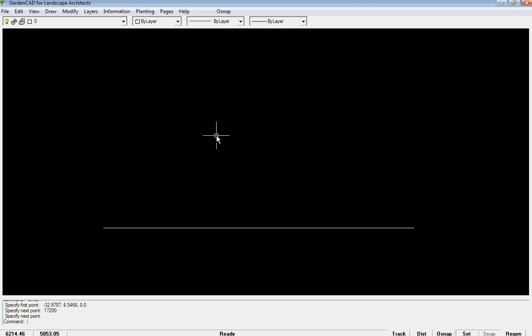So let's go draw line again, and what I want to do is to latch onto the end of that line. You notice as I get near the end of the line, a yellow flyover appears. So now I want to draw a line up in this direction. You might notice that as we hold that tracking device, the cursor is jumping in steps of 100 units. So I want to go 7 meters across. Now I could type the 7 meters, but I could do what I've done there, just let it hover over the 7 meters and hit the enter key, and nothing happened, did it?